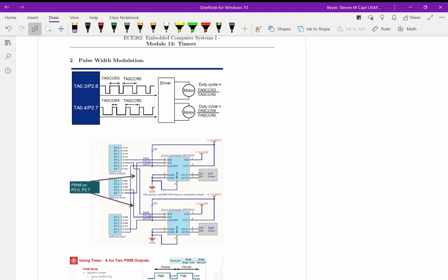The second thing we're going to look at now is how we would use this timer with pulse width modulation. Dr. Beck taught you a lot about motors, taught you the benefits of pulse width modulation, how it's better than some of the other options. But what you then implemented was turn on, wait, off, wait, repeat. And to do that, this wait right here blocks, which is not great because then you can't do anything else.